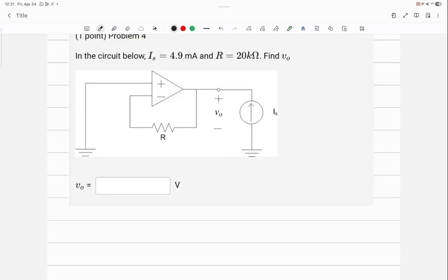Who's next? Jonathan. Do the whole thing yourself. I positive and negative is 0. I positive is 0. I negative is 0. What else? Your V positive and your V negative are 0 volts. Based on what? Why? So start from here. V positive is 0. That makes the V negative to be 0. Okay?